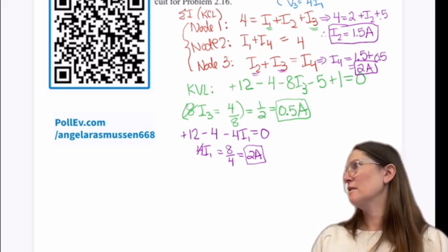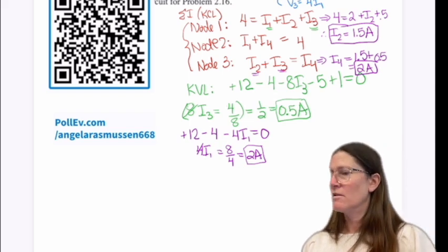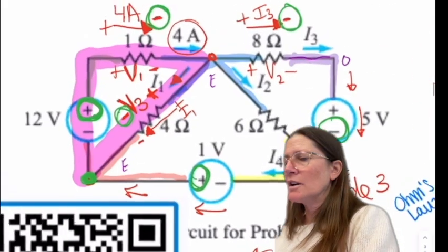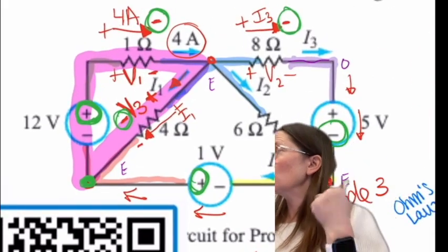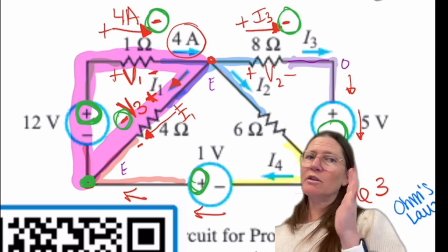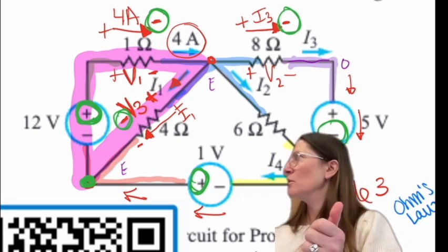Yes. So how did you get for I1? Because you were solving for I1. So I know 4 amps. Do you see that there's 4 amps going through there? Okay, you know 4 amps is going through it. So I use the I times R. I is 4 amps, and then the R is 1 ohm. Oh, okay.